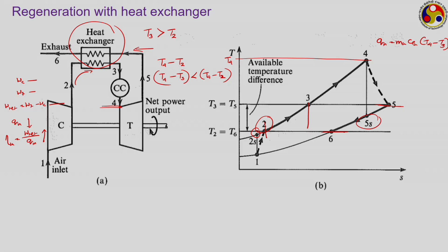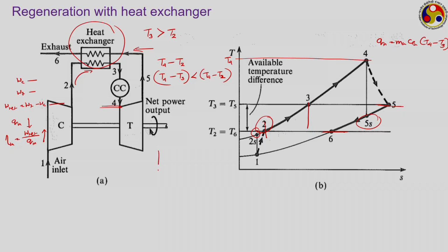We generally go for a counter flow kind of heat exchanger. Let me show from this diagram only. A counter flow heat exchanger arrangement is shown. So, as the air is flowing in this direction and the gas is flowing in this direction, air is always encountering gas at higher temperature, because at the inlet the air temperature is low, and similarly at the exit the gas temperature is also low, and they are in close proximity of each other.